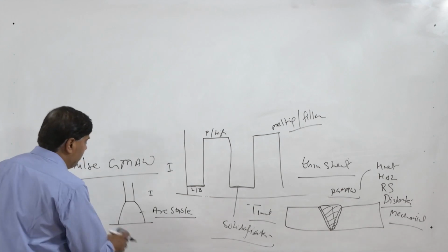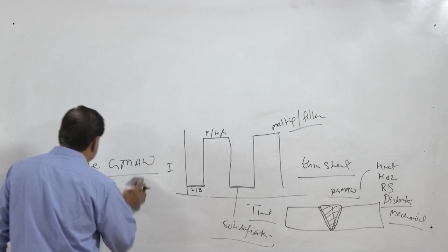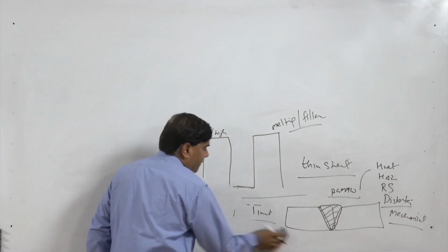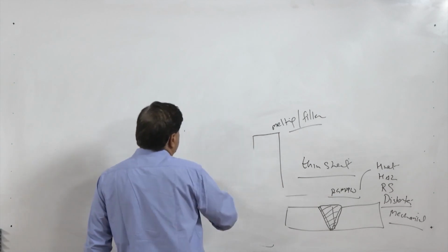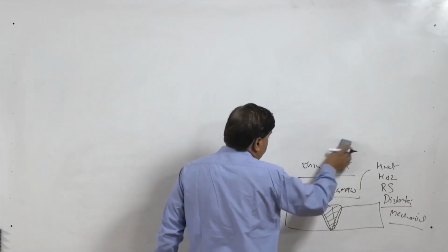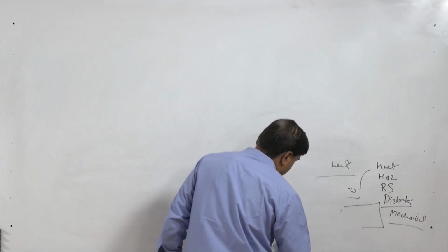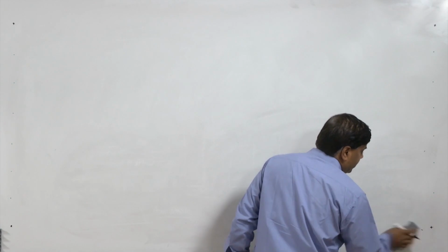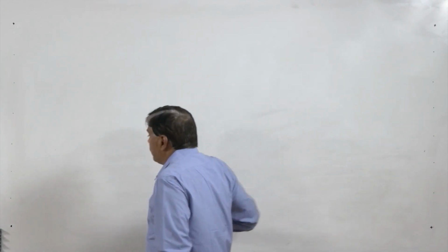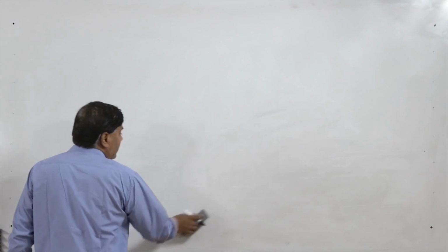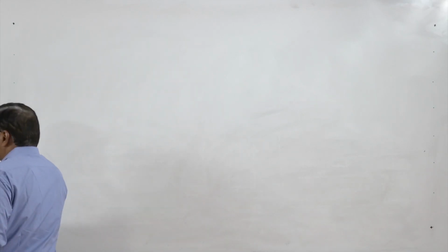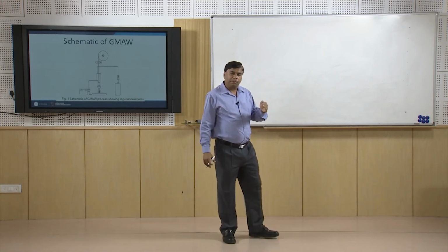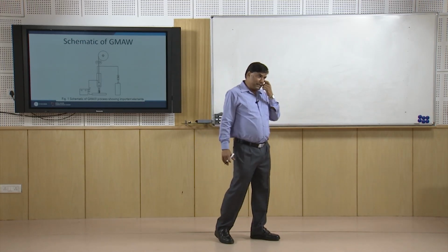In conventional GMAW, we supplied only the constant current and the constant voltage for the development of the welding arc, and heat delivered was also constant during the welding. But in case of the pulse GMAW, the value of the current was regulated between the peak current and the background current levels, so that the melting and the solidification can proceed sequentially step by step.